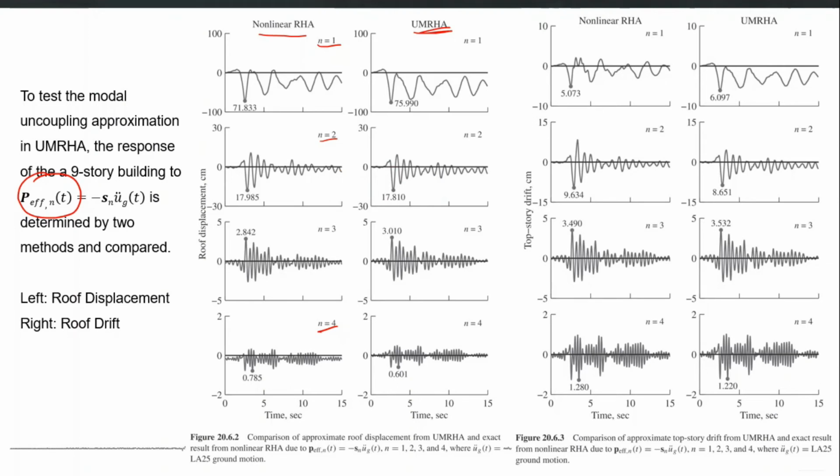So this shows that UMRHA has the potential to be developed further as a seismic analysis procedure, but the main issue is whether we can get an accurate force deformation behavior for each modal single degree of freedom system.